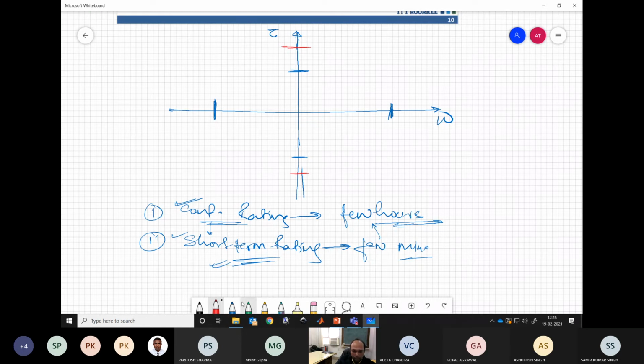Now, it is not like when we are drawing the limits on these parts, you can have any torque for the entire speed range. No, we cannot have, because there is another quantity on which we are putting restrictions, the amount of power drawn. So we can have constant power operation for some range of omega, but we cannot have the same power being fed for the complete range.